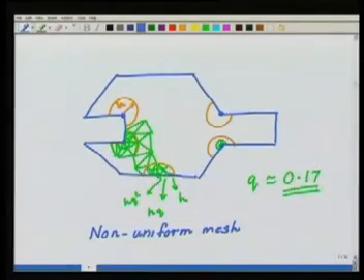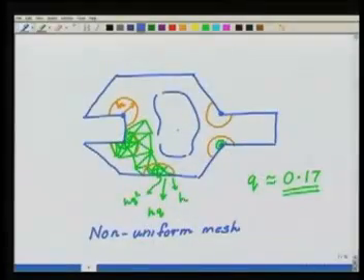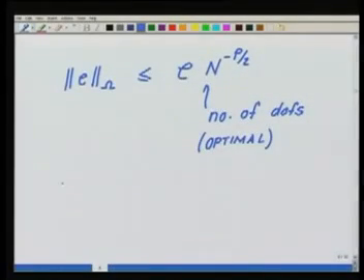Okay, so here if I take these refined meshes and a low P and I keep on raising the P, such that away from the corner the solution is smooth. The solution is only unsmooth in the vicinity of the corner, then in that region using large elements with high P will give very good accuracy. And that is exactly what we should do: use large elements with high P, small elements with low P, then in that case we can get essentially exponential accuracy. So when we do HP version of the finite element solution, then I can get exponential accuracy.